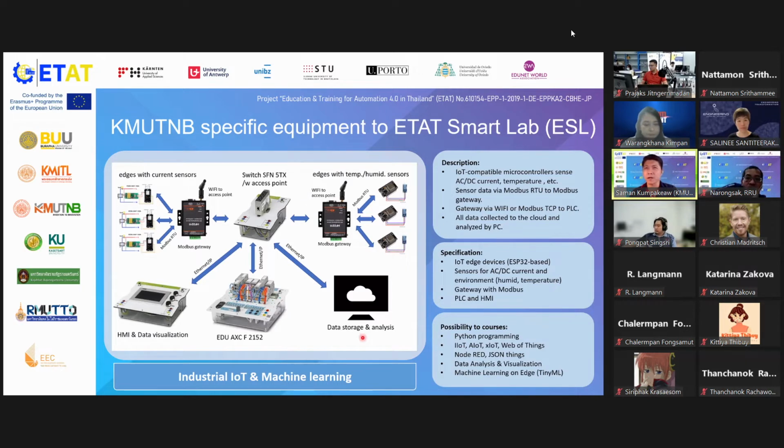PLC Next has an extra cloud service which we call Profi Cloud, where we can install data, and our system will be controlled by the PLC itself, and can be monitored either by the HMI screen or on the web browser.